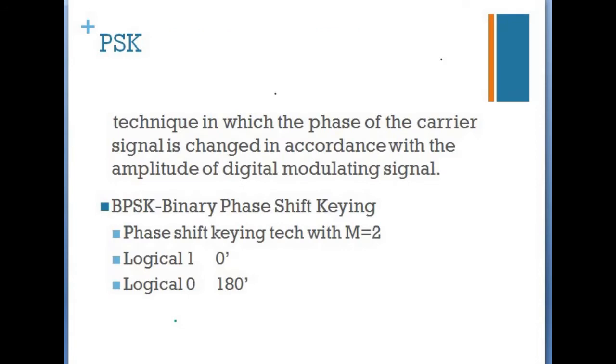So PSK is a digital modulation technique in which the phase of the carrier signal is changed in accordance with the amplitude of the digital modulating signal. Based on the number of possible changes in the output, that is the modulated signal, we have different types of PSK. Binary phase shift keying is the simplest form of PSK. It is also called phase reversal keying, and sometimes biphase modulation.